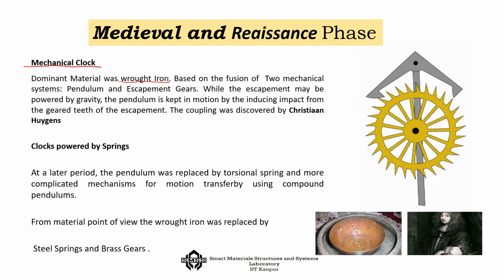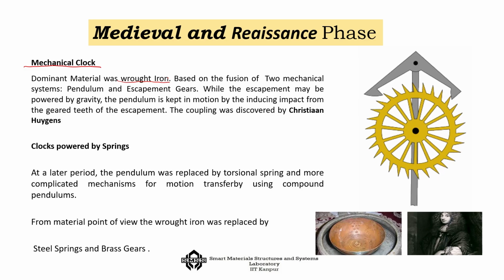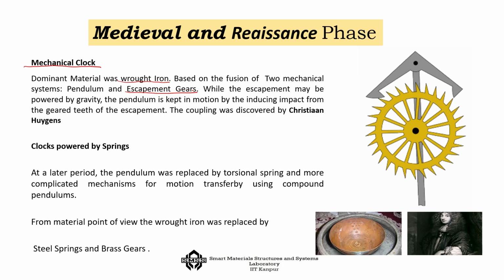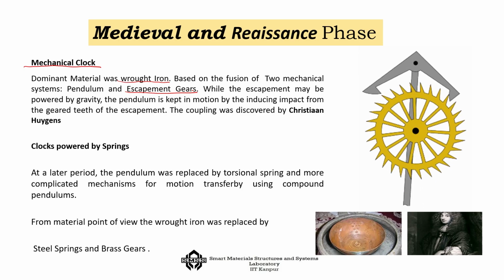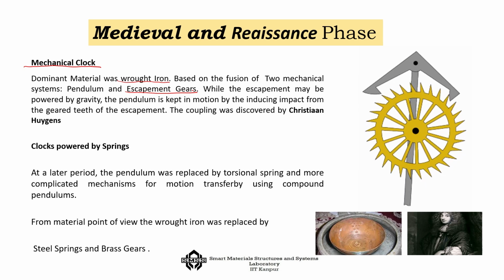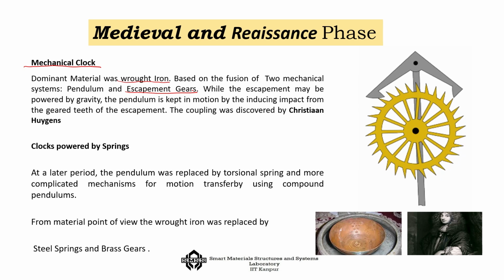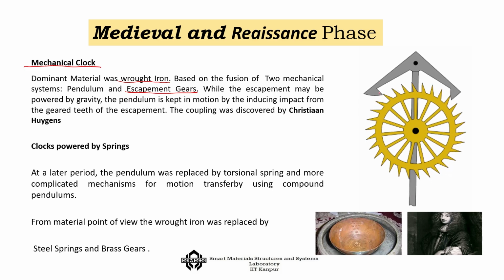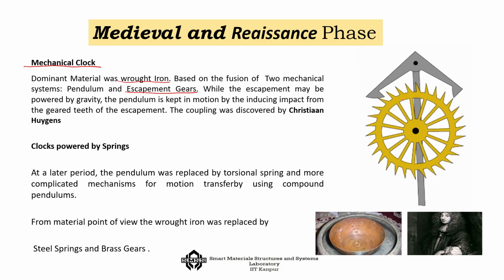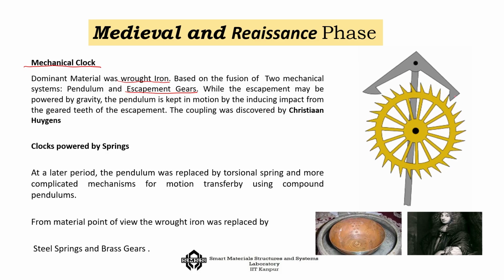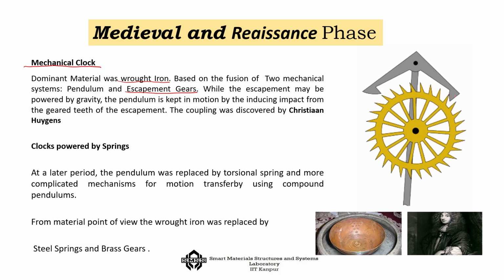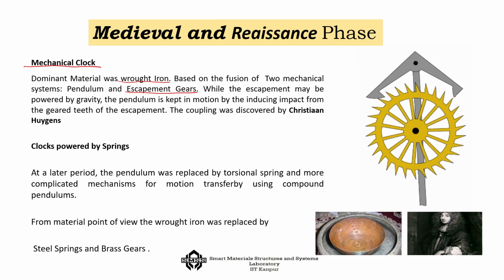Now the one important thing that helped there is the escapement gear. So what is an escapement gear? If you look at the right side animation, it will be clear to you that in the case of an escapement gear, every time the left hand one is hitting, it moves by a finite amount, and then it stops on the right hand side. So every time, with its help, you can divide the entire time of rotation into certain finite durations.